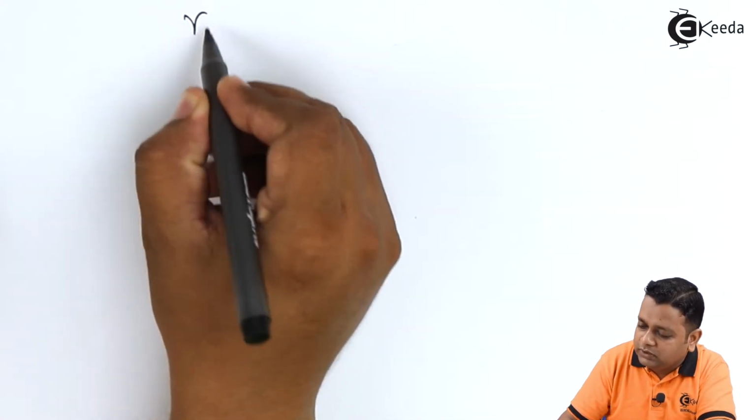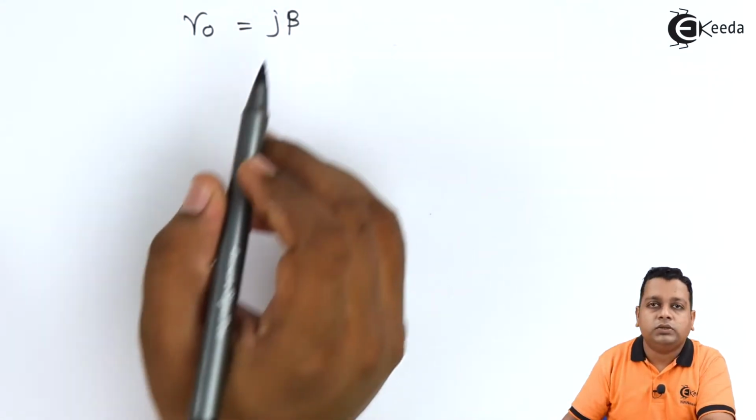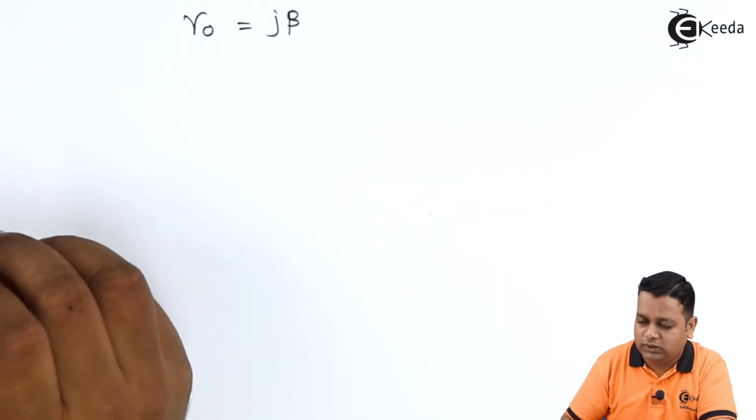Now it's time to analyze the working operation of the carcinotron device with the help of mathematical equations. As in the previous topic, where we went through the solutions with respect to the propagation equation, here we set the secular equation with the help of propagation constants. So first of all, we set gamma suffix 0 equal to j times beta, where beta is the phase shift constant.